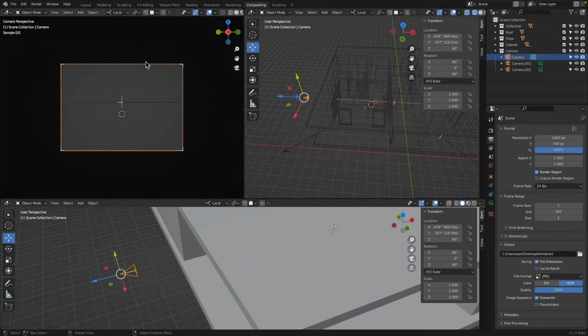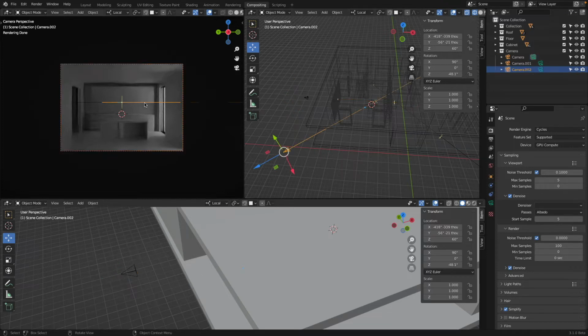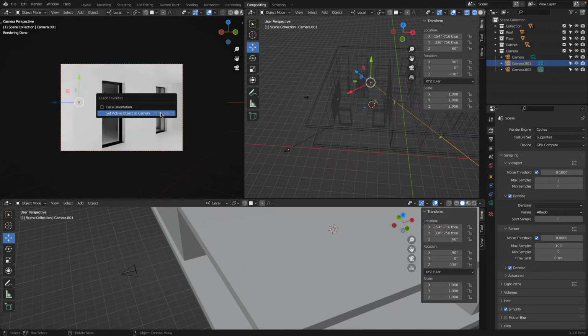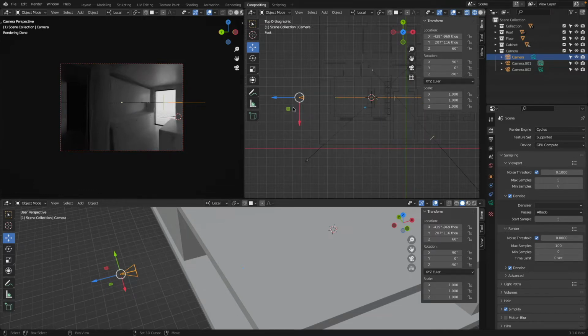So Z and render. Okay, there we are. I have my settings set up, so denoise is 5, max sample for viewport is 5. It's very bloppy, it renders fast, it lacks a lot of detail, but it's sufficient to understand how something looks. So you see how I quickly switch between my areas. Oh, that's actually also nice how the light comes in and all the stuff. Maybe this brings the idea of, well, maybe one more.